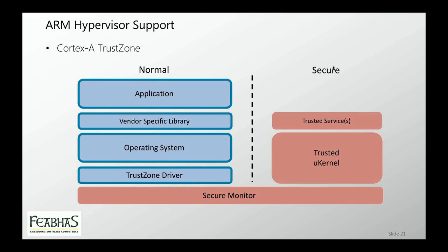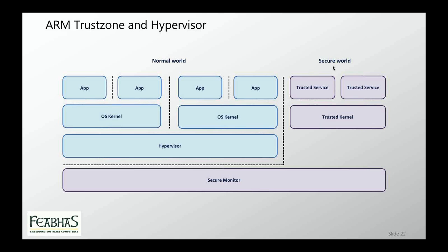So there is a first degree on certain Cortex-A where you do actually have a degree of paravirtualization using this secure, non-secure mode. Even though you wouldn't necessarily want a secure environment, you could run your real-time operating system in a secure environment and run Linux, for example, in the normal environment, and that will give you a form of paravirtualization straight away. But in addition to that, especially on the Cortex-A series at the moment, there is also separate support for a pure Type 1 hypervisor as well. So you can have TrustZone and/or hypervisor technology.